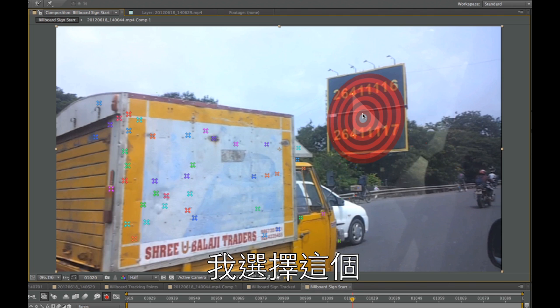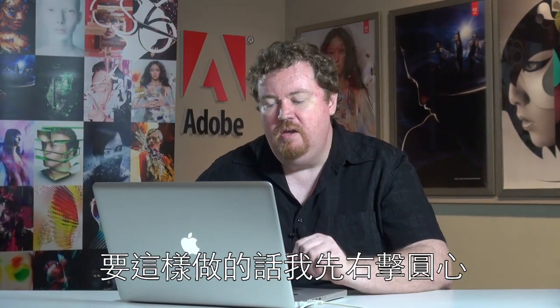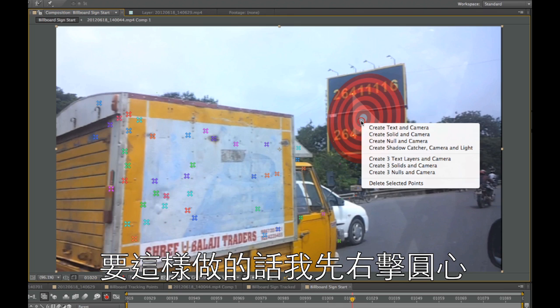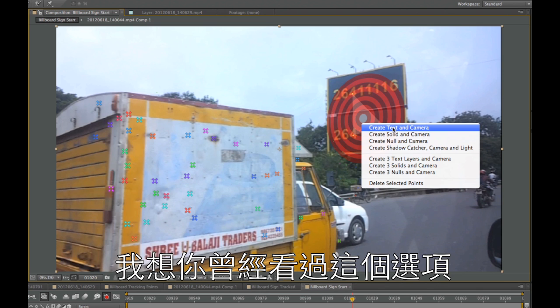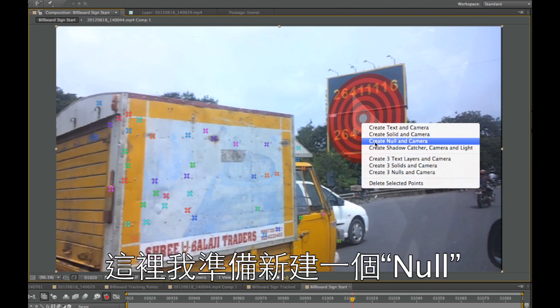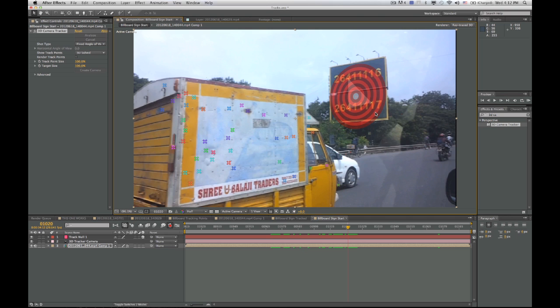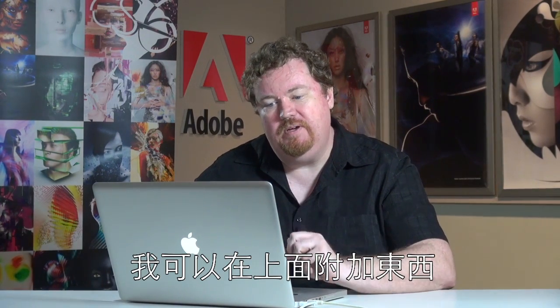So I'll select that, and I want to put a picture onto the billboard. To do that, when I right-click on the bullseye, I can choose between creating text, which I'm sure you've seen already, or creating a solid, which can be useful. In this case, what I'm going to do is create something called a null. A null is a little invisible object that acts as an anchor, and I can attach things to it.